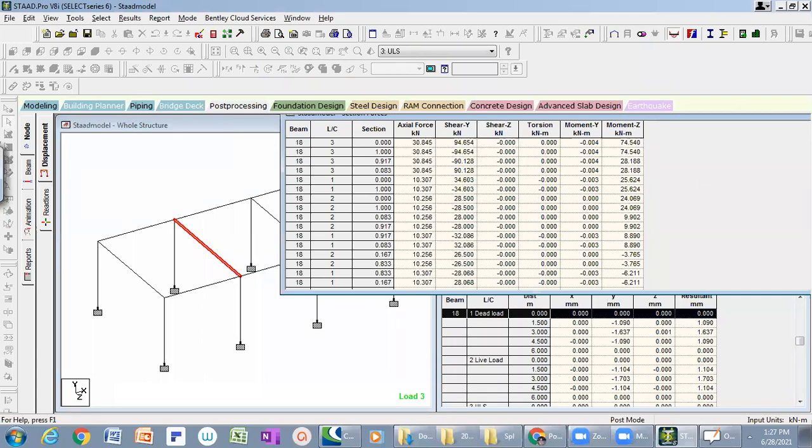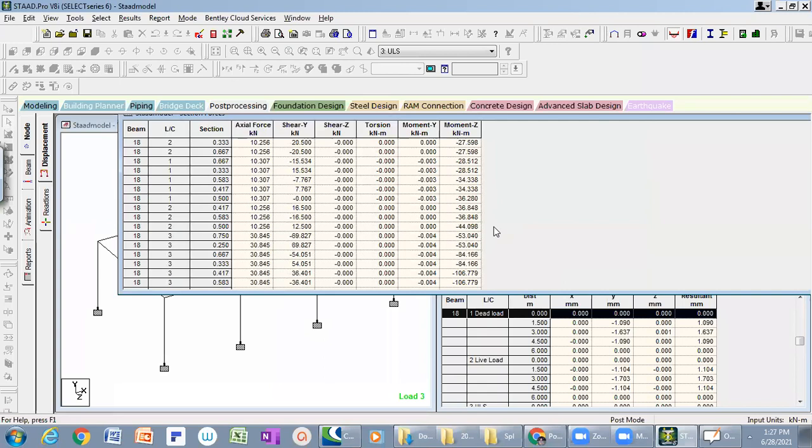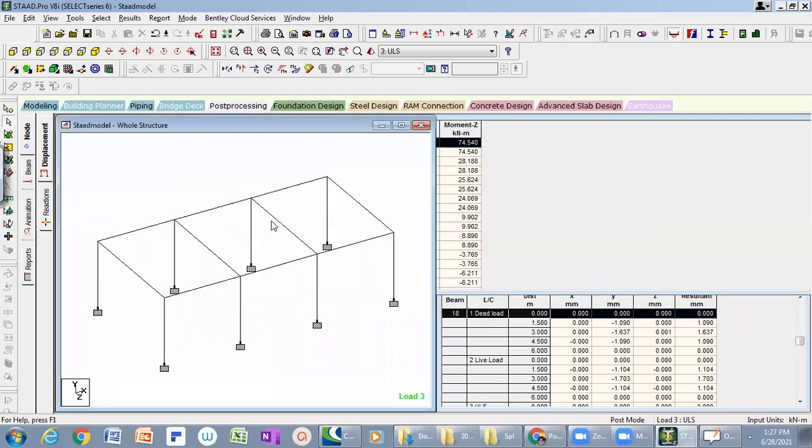And if you want to see the sagging value, you can scroll down and you could see the maximum sagging value, right? This minus 120 denotes the maximum sagging value for this beam, right? Okay. Similarly, if you take another beam, for example this particular beam, or the whole set of beams, you take all the beams and you need to find the maximum value for this set of beams.